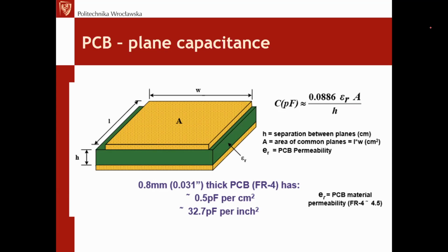It is a problem if you are designing a high frequency transmitter, because high frequency transmitters can require a few watts of power, which has to be delivered from the transmitter to the antenna, and then we have to design the high frequency tracks properly so they don't burn.